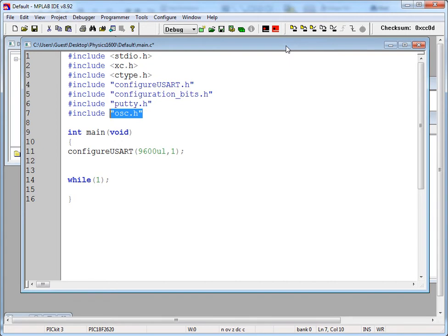I'm going to make you set up all 10 possible speeds. So if I wanted this to work at 2 megahertz, set _OSC to capital M, capital H, Z, like that. Set the oscillator to 2 megahertz. Get rid of that. And if I wanted this to work correctly, I just set it to 2. So I will have you set up all these different frequencies.